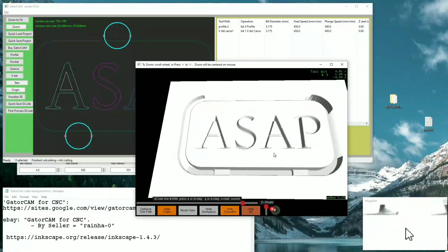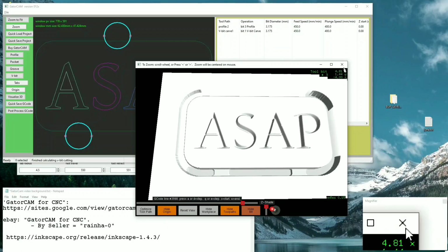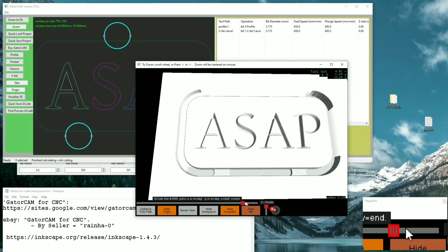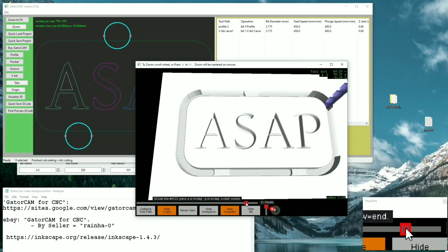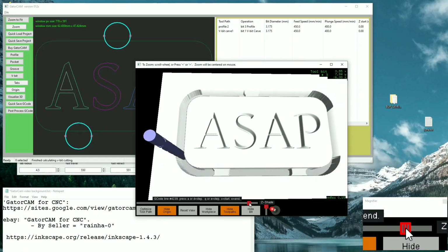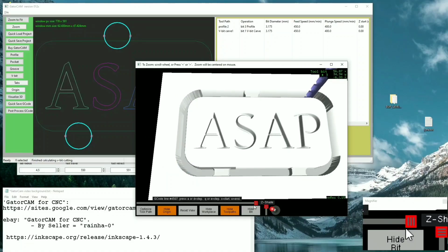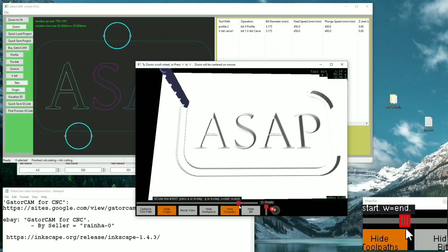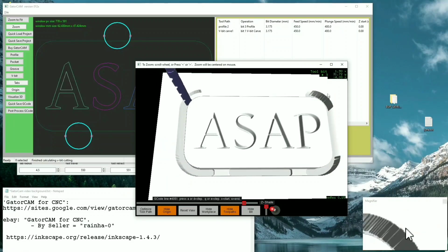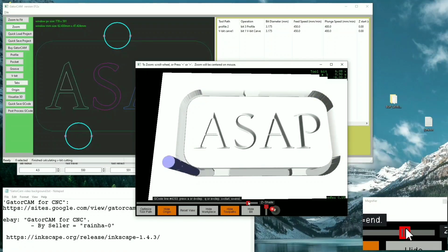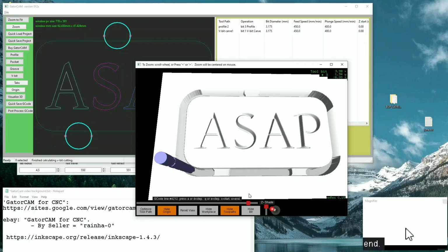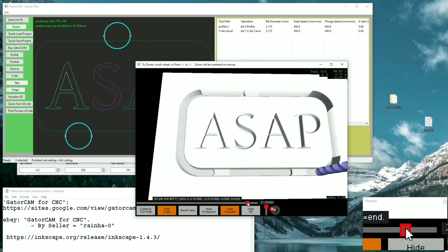So let's see what else. Okay, the tool bit X, Y, and Z over here shows you the current position. So if you want to verify everything is correct, you just look at that. So here we can see Z's at -2, next pass -4, right here. And next pass is -6, except it still steps over for those tabs if you watch.